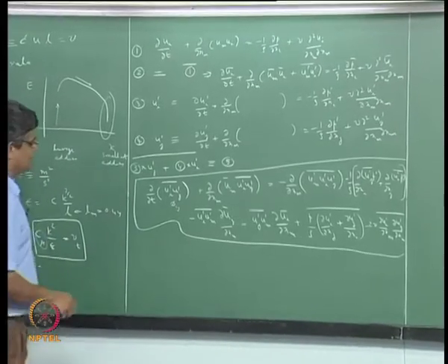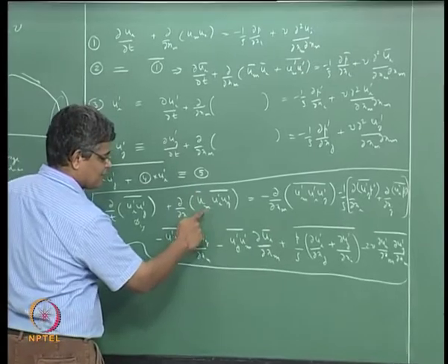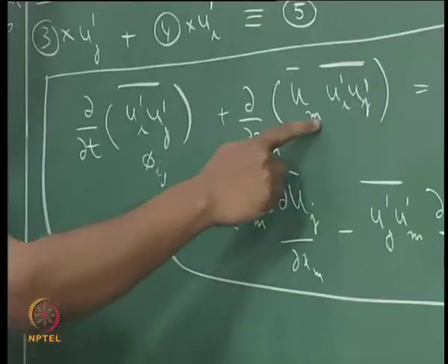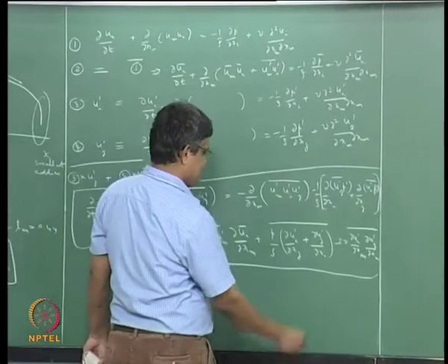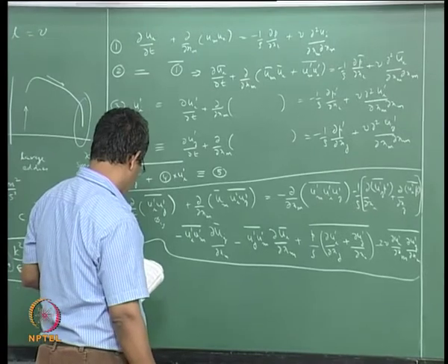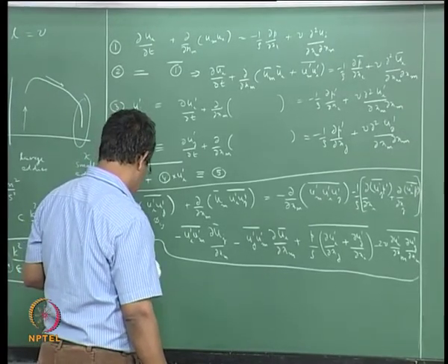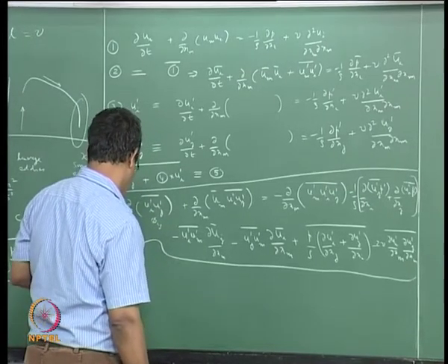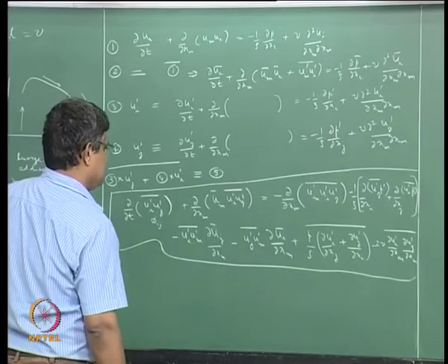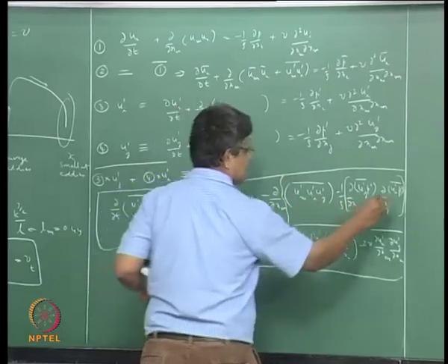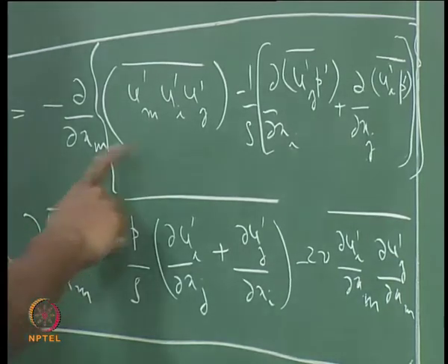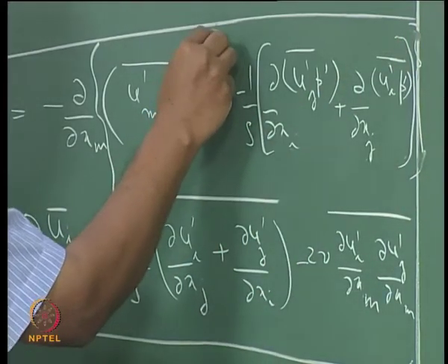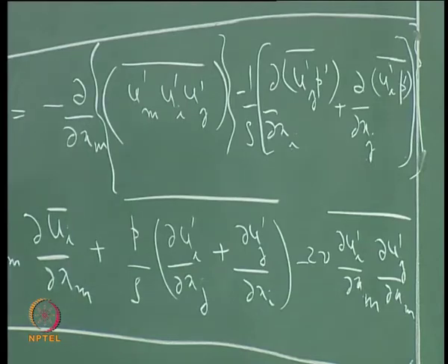This is a stress here, and this is the advection term. This is being advected by the mean flow, that is the mean velocity here, and gradient that is coming here, so the divergence operator. And we are missing... oh, no, this is correct. Okay, so we are missing a term which is in the generic scalar transport equation.